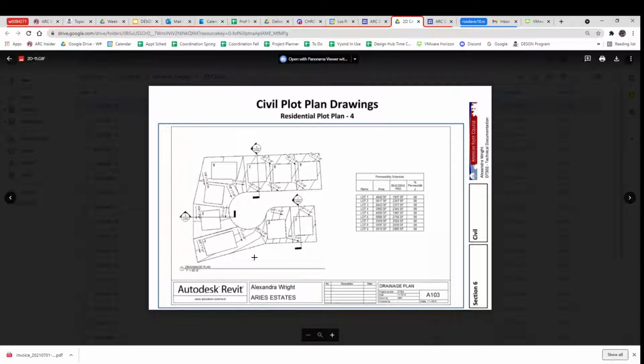So since these ones are going off-site in this direction, the planning department would either require a mitigation along this lot line, something like a swale or a French drain, or they would ensure that this property owner will accept this amount of drainage coming off of the property. And since there's a percent permeability of this ground, which all comes from geotechnical work, it could be that this drainage doesn't really affect anything.